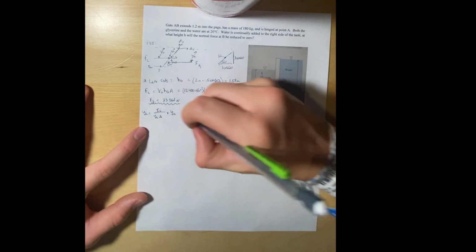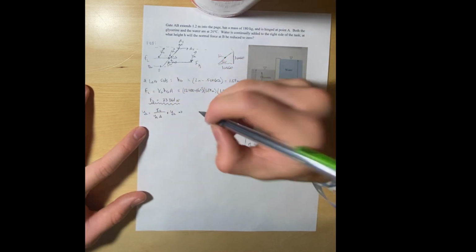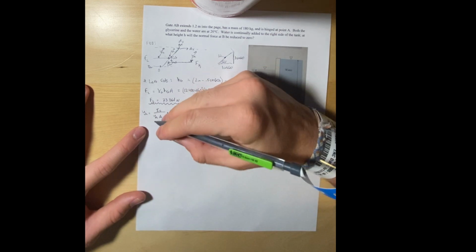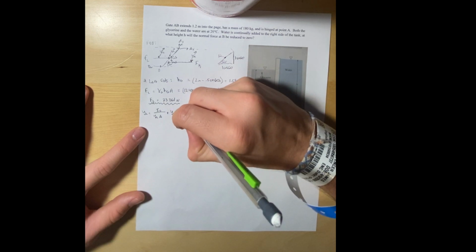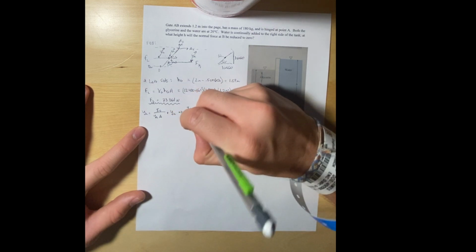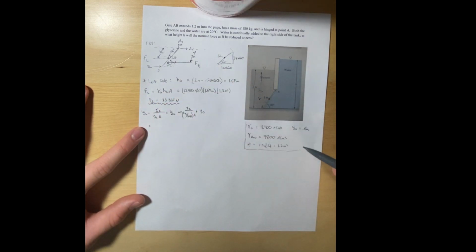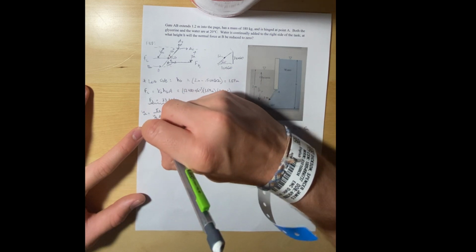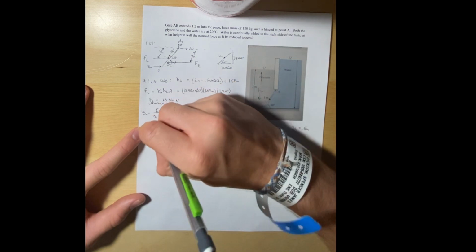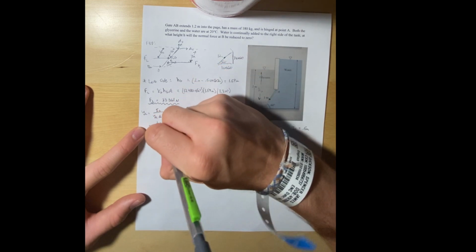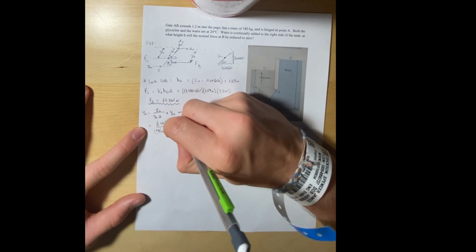All right, anyways, when we plug our numbers in here, actually simplifying this down, the y sub L term goes to the moment over hg over sine theta times the area, plus y sub c. When we plug our numbers into this, it's going to give us 1/12 base times height cubed over hg sine theta plus y sub c.